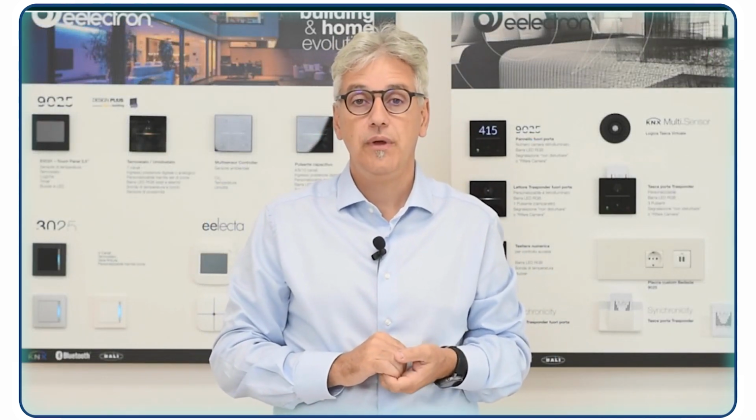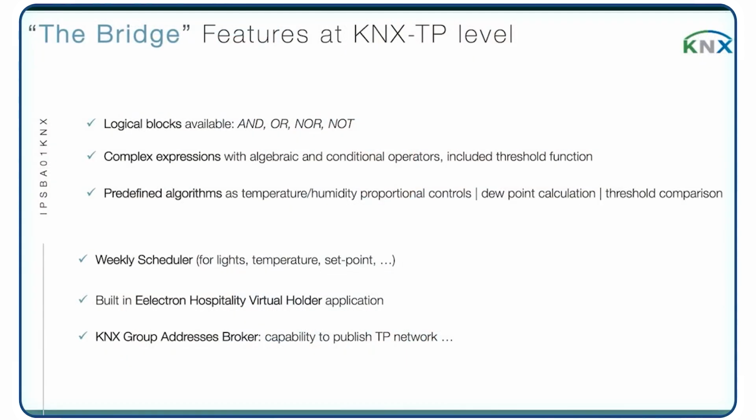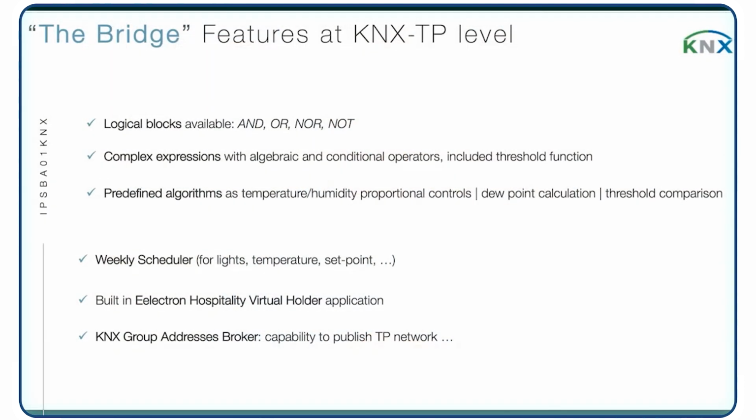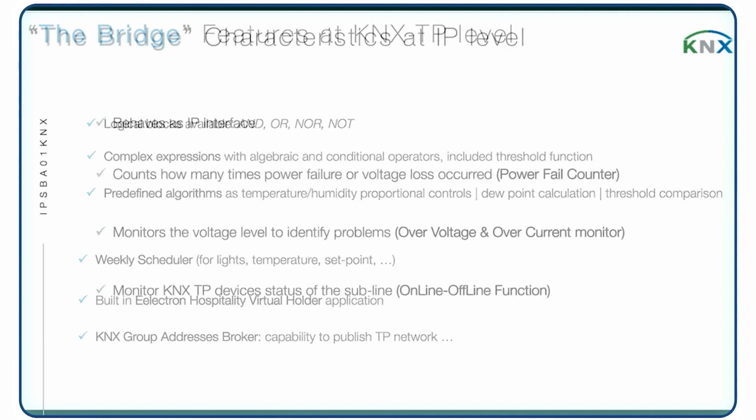Aside of the main feature as an IP interface or KNX power supply, we have other functions built into our bridge. So we can program logic inside the device, not only AND or OR, let me say simple function, but even complex expression. We have a weekly scheduler to program a weekly event, and we have also a surveillance module.